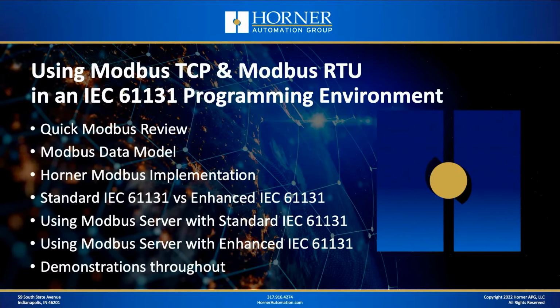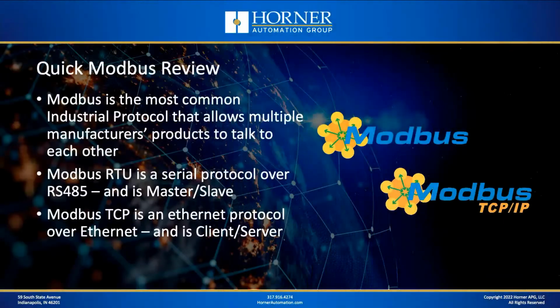And then for each of those 2 options, we're going to talk about how to implement Modbus as a server on your OCS. So if your OCS is controlling a machine and you want some of the variables in the OCS to be accessible over Modbus from a SCADA package or something similar, you'll be using Modbus in server mode in that case, and we're going to tell you how to do that. And of course, we're going to have plenty of demonstrations throughout to show you what you need to do. Let's get started. Let's do our quick review of Modbus.